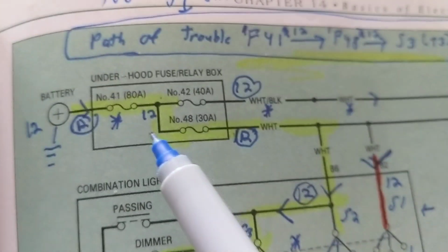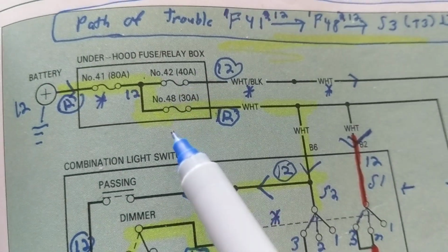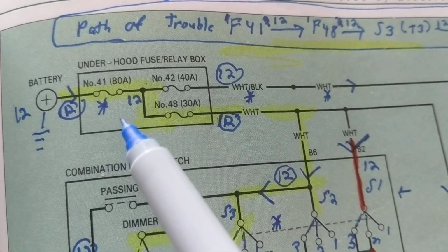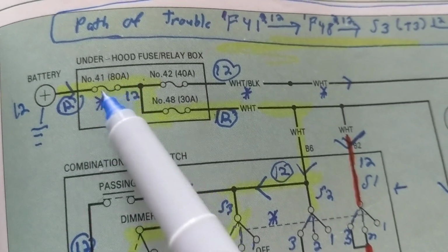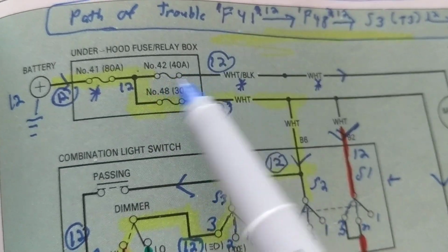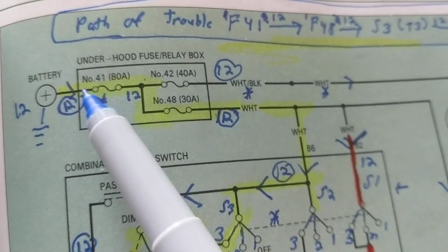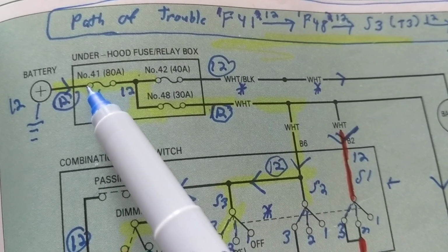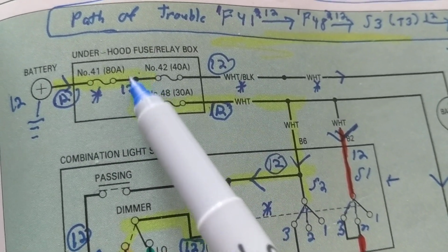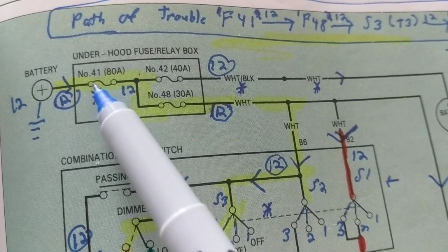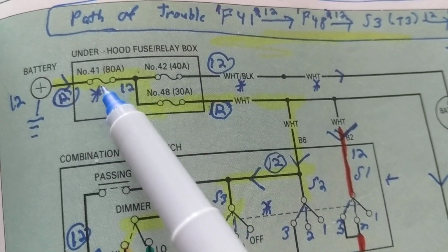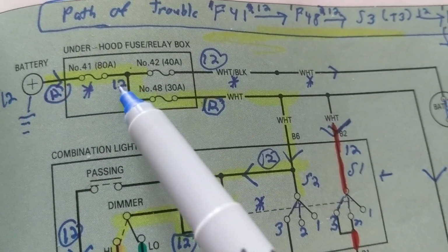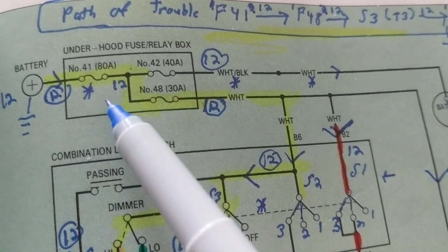Now, how much will it take to blow these fuses? The question was introduced. If I have 80 amps, that means if I have 90 amps, this will blow. Not these. This will blow first. So at 90 amps, I'll go over here. How much will I measure on this side? I'll measure 12 volts here, and when I put my meter to the other side of the fuse, I'll measure 0. Why? Because this is open. It's like nothing is in between. No jumper, nothing. No wire. Therefore, this is not connected to battery. So 12 volts here and 0 volts, boom, I have a problem across this fuse.